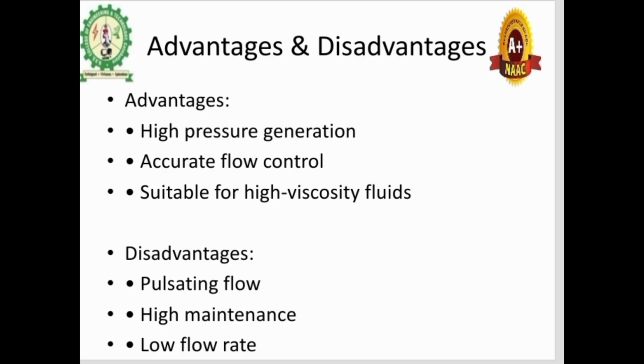And when considering the disadvantages of these reciprocating pumps, the flow is pulsating, the cost of maintenance is too high compared with other pumps, and the flow rate is low. So these points are considered as the advantages and disadvantages of reciprocating pumps.